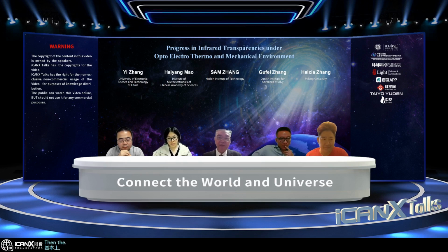The way of making is usually using a powder mechanical process: powder contained in a container, then pressed and then sintered. In this process, you have much more uncertainties, like point defects, even cracks. So that's why the hardness is lower than the thin film.